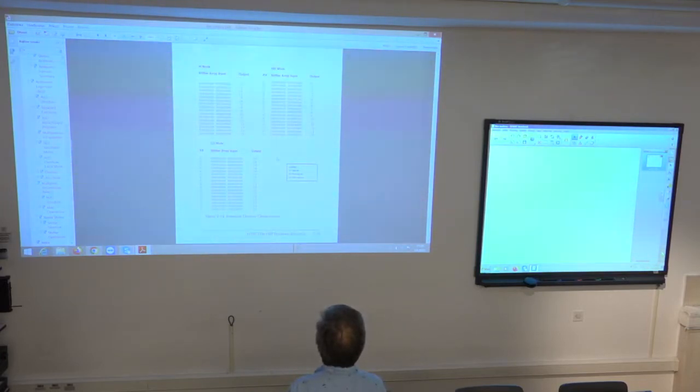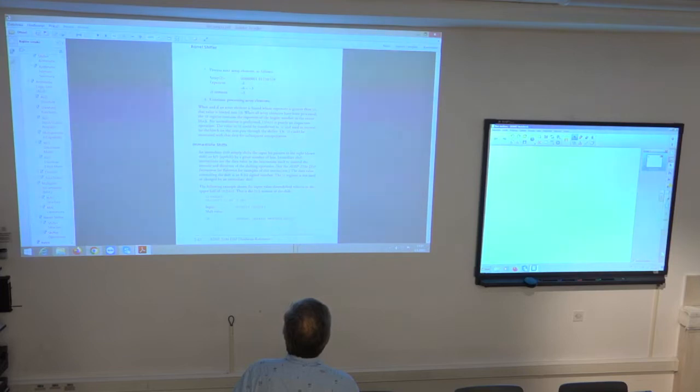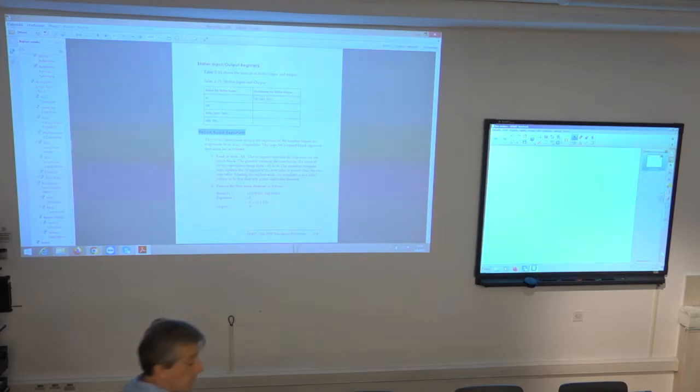There are several examples of how this exponent detection works and how it is combined with the normalization instruction. There is also one special instruction that enables detection of a common exponent of several numbers, or a block of numbers. So for example, you have 128 different values, and you want to find how many bit positions to the left they can be shifted without causing overflow.